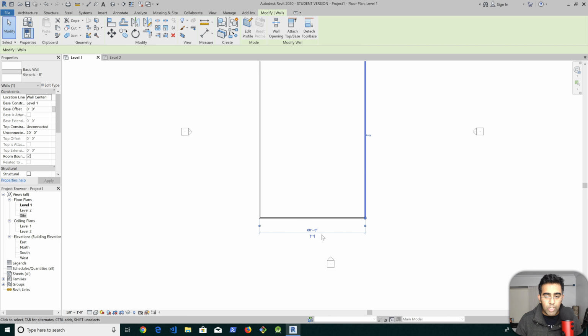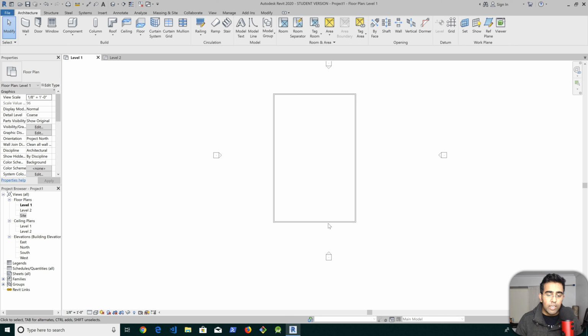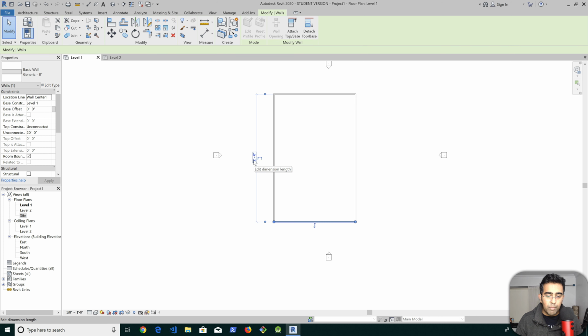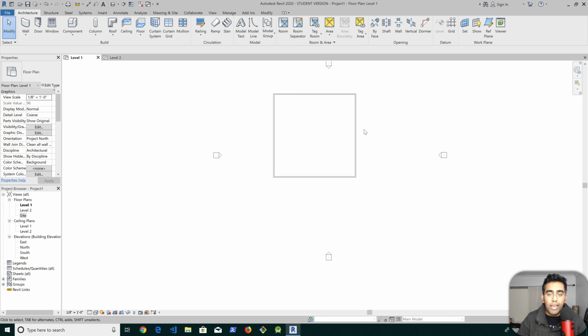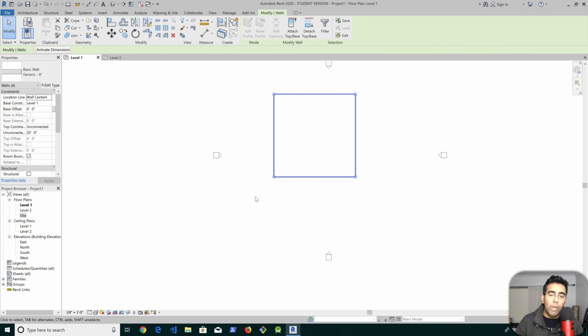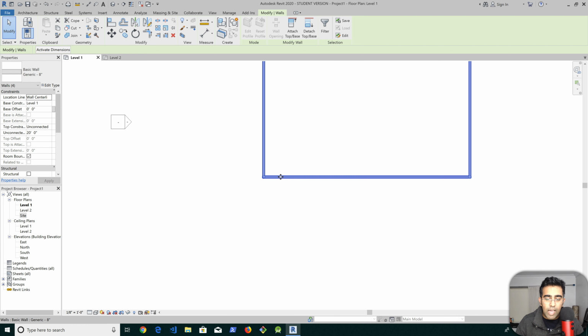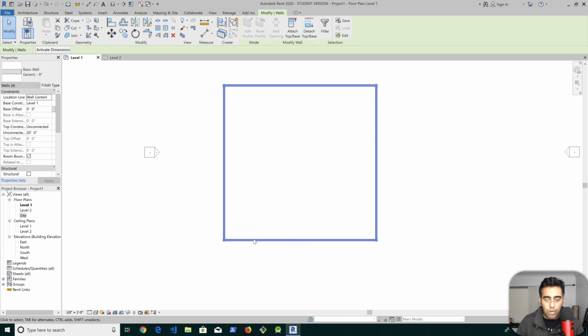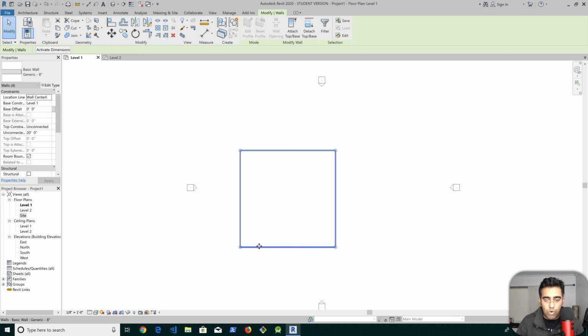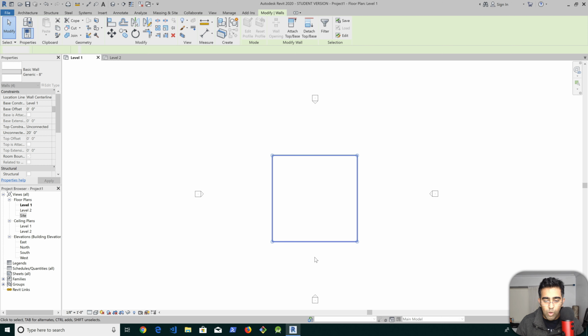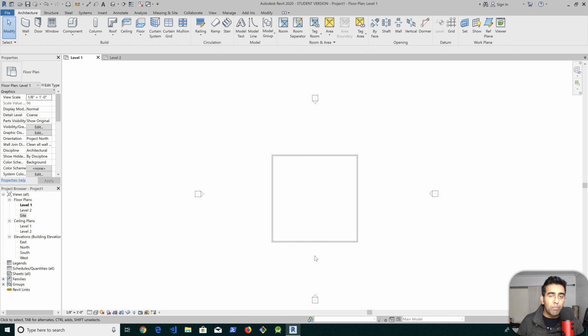So what about changing the height for the boundary? Well, you're gonna select this wall, and now you have the boundary coming here. So I'm gonna change this to 0 inch, and I'm going to change this to, let's just say 60 as well. That will make an exact rectangle. Now you can do selection by click, hold the mouse button down and drag, and then you'll select multiple objects. Now you can see that the icon of our cursor is like a move. So I can click and just move that object there. All right, I'm gonna try putting that in the middle. Also, I'm gonna click outside, which will get me out from selection.